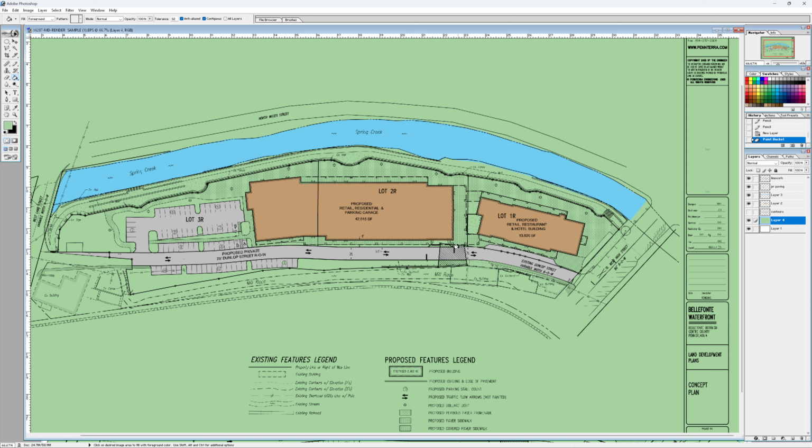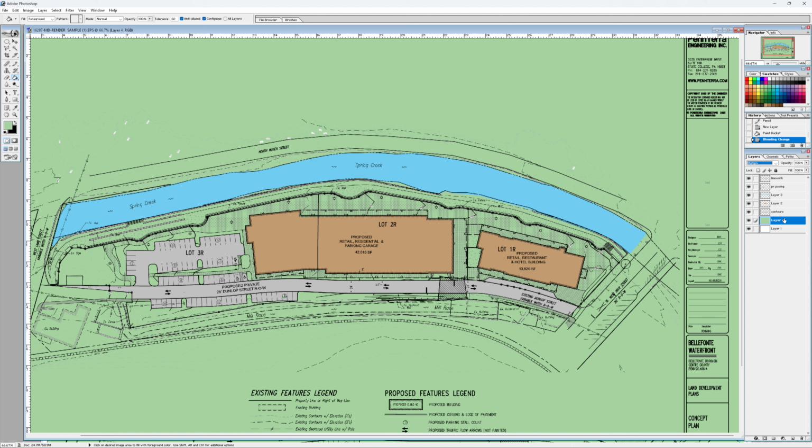In this case, green is great, but boy, it's a lot of green. Don't really need that much. I'll turn on my contours layer. Hey, that adds a little bit more. You'll notice there are some issues with masks showing up as white. That can be solved by changing the layer state to multiply, because white doesn't multiply anything. Oh, did I not do that? I didn't do that to the right layer. When you multiply, the white doesn't make it any darker, so it clears that up. That's one way to get around those kinds of export issues. Let me see, layer.